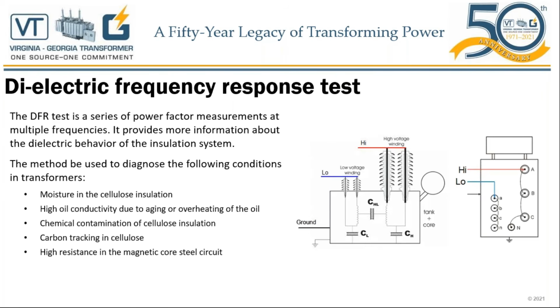Dielectric frequency response test, DFR. This is not SFRA, this is DFR. The DFR test is a series of power factor measurements at multiple frequencies. It's a special test equipment, and this is what it does. It provides more information about the dielectric behavior of the insulation system.